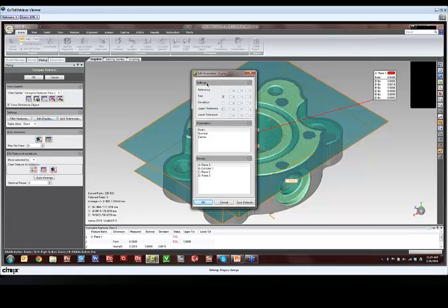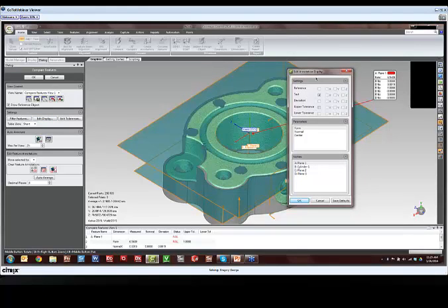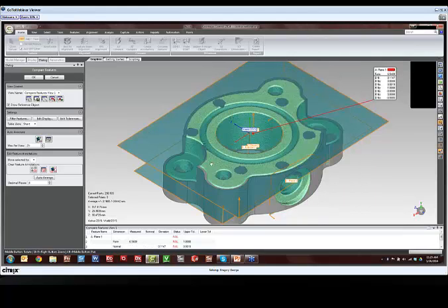Now if I want to change what it displays for this plane, I can change the normal direction, and I can say I want to show the normal deviation between the plane on the point cloud and the plane on the CAD model, and it updates my annotation. And then just like before, I can save the views and I have my table.